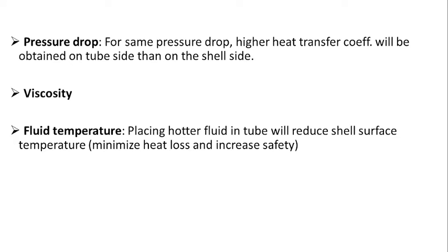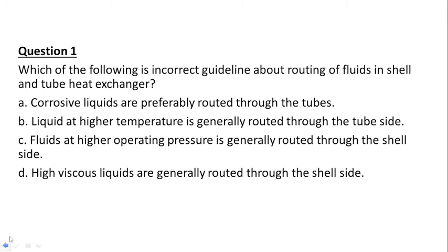Then next one is the viscosity. Higher heat transfer coefficient will be obtained by allocating more viscous material on the shell side. So more viscous liquids are preferred in the shell side of the tube. So option D is actually correct.